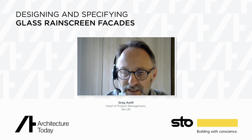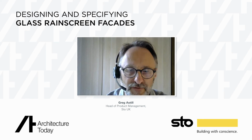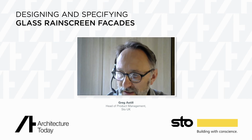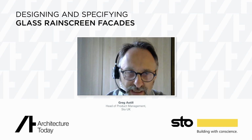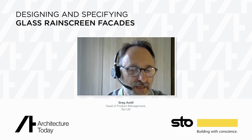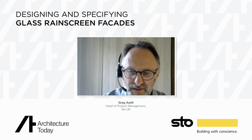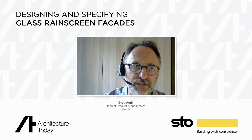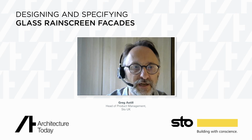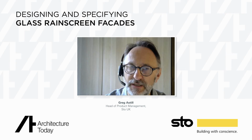Rainscreens are particularly good at dealing with moisture from the inside. If you have a breathable wall, any moisture that comes through is taken away rapidly by the ventilated part of the ventilated Rainscreen, that air gap on the outside. But also, typically with steel framed structures, if you've got a light steel frame that you're putting a sheathing board onto, these can be particularly tricky when it comes to condensation.